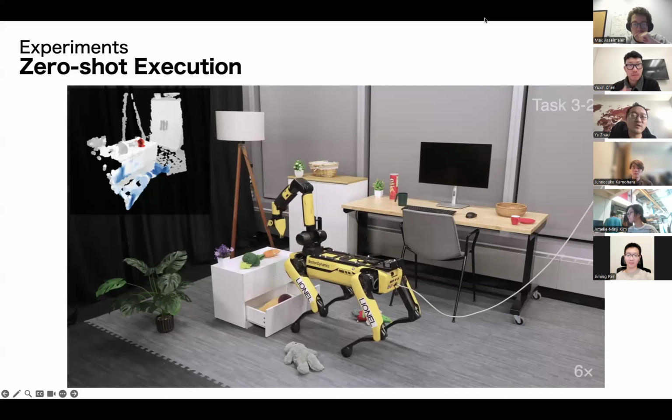So the diffusion output includes what? Does it include the grasping position and the grasping pose? No. The diffusion policy just outputs the joint command. It's just the pure imitation learning policy. Okay. But given different objects, where to grasp and what pose to use to grasp, that's all implicitly encoded in the joint command you calculated from the diffusion.